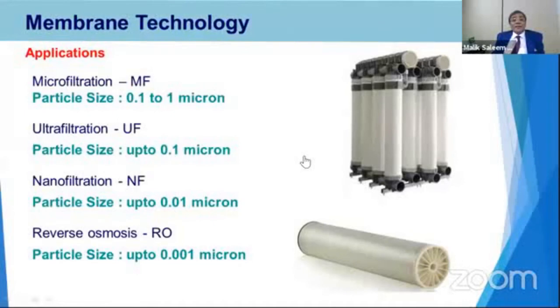Now, we will discuss the types of membranes available in the market and on which R&D is going on. Microfiltration membranes are basically cross-flow membranes. And every membrane is a molecular sieve, like you want to sieve any molecule from the liquid in which it is dissolved. As in the case of water, we have sodium chloride, calcium, magnesium, sodium in various forms, calcium carbonate, calcium sulfate. Every molecule has a different molecular weight.